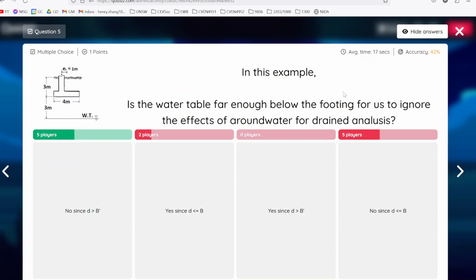And if this is the width of the footing, call it B, B dash is our effective width, right? And the effective width has a formula. It's the regular width minus 2 times the eccentricity. The idea behind this is that this area of the footing is our effective width, kind of. So you reduce the total width of the footing based on how it's loaded, okay?